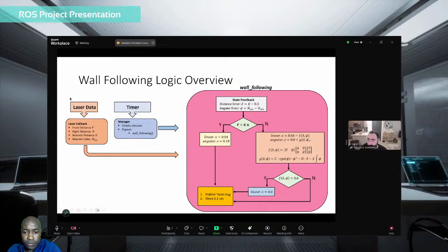So this is the feed-forward controller I was talking about. I have this nominal state, which is the max speed that I'd like to move at, which is 0.06 for linear direction. And depending on some function, and I'll go into what that function is, depending on the size of this error squared, I will have a reduction in linear speed. The reason I chose to do this is because when we're moving quickly and errors arise, either from miscommunications or whatever happens, if we're moving fast, then those errors can accumulate really fast. They are amplified, I guess is the word I might use.